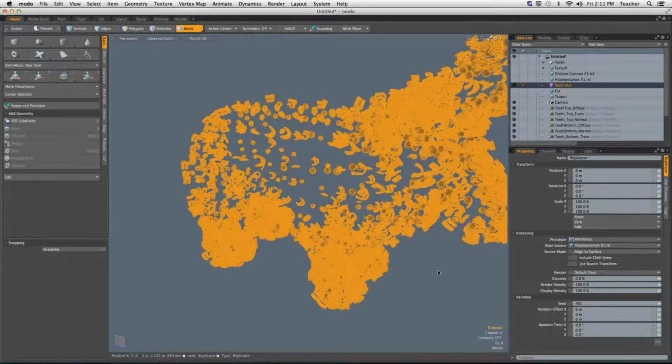Looking at the location of these vertices, some are teeth, some are eyeballs, some are the ears. It's just kind of weird, right? But it's also kind of great. Okay, it allows us to randomize the detail that's being inserted within the scene. This is really great for environmental stuff. I've used this a number of times for trees, right? Because you look at a forest of trees, it's not all the same tree, right? There are variations of the different trees inside the forest. This is a great way to get different trees quickly without having to place them by hand. Okay? Replicating a group of items instead of just one item.